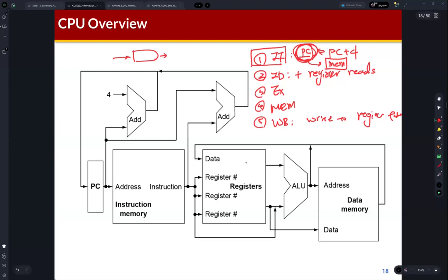So we can implement this instruction fetch operation like this. You can find the program counter here. This is actually a register, and we can implement the register using D flip-flops, right? If you took the digital logic design course, I believe you can remember that a register is a group of D flip-flops. And then we can store temporary data in this register.